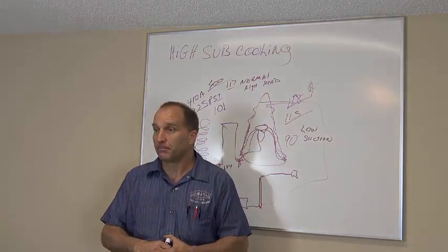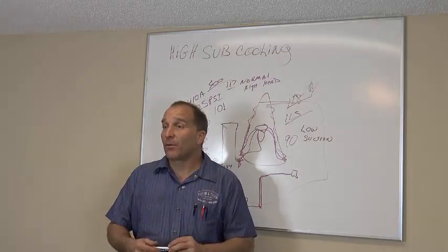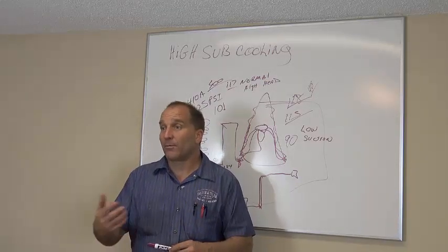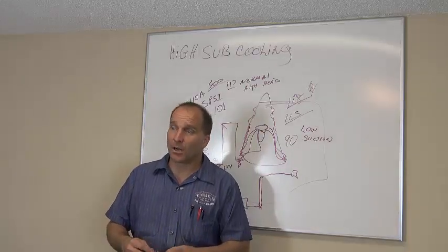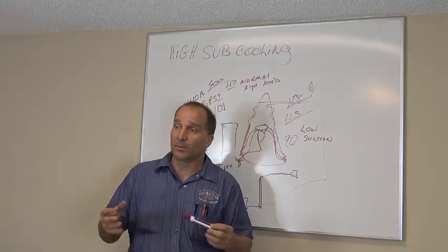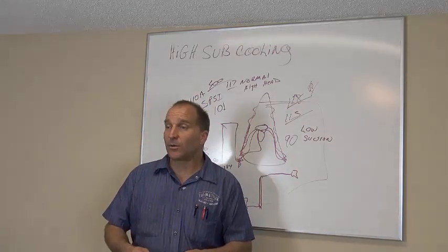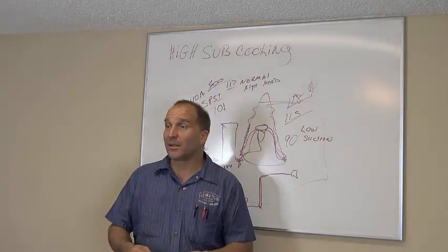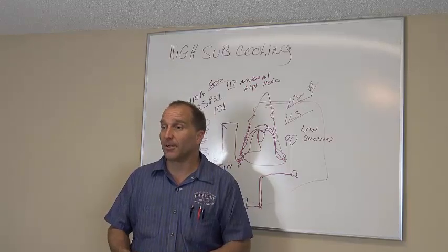Why wasn't I told this last time? The reason you weren't told is the guy might not have thought it was dirty. One of my jobs when I come here today is to make sure that your system works at 100% efficiency. So I'm checking your system out right now, and your head pressure's running a little bit high. I checked your history, and I've seen that it was not done last time, so that's why it really needs to be done today. I can do it for you right now if you'd like.